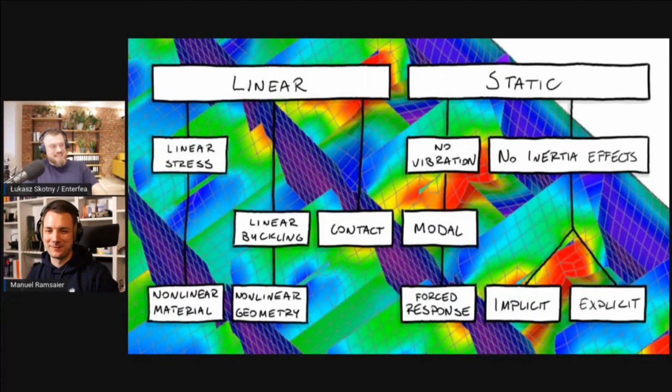Right? To me, inertia effect is just a thing that if you swing a fishing rod in real life, if you do it fast enough, you will actually bend the rod by the act of swinging it. Yes. And you can do whatever nonlinear geometrical analysis you like, there's nothing like this. If you would apply a rotation at light speed to the tip, it will just nicely rotate like this. Nothing would wobble, nothing would shake. It would be like plain, nice rotation. And inertia effect basically does this. That things, as you start to move them quickly, they react with inertia.